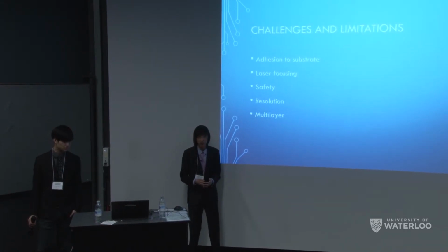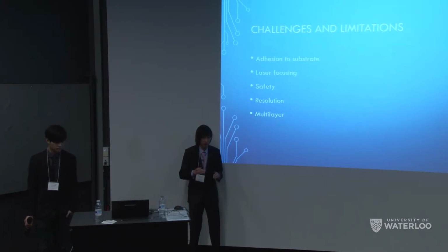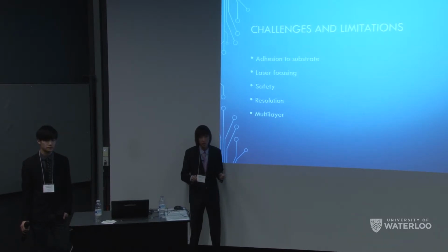Another thing was the laser focusing. As the height of the substrates, or the height of the powder bed, wasn't perfectly uniform in our prototype and in our demonstration, it was difficult to correctly focus the laser so that everything would reach the correct temperatures for sintering. And safety is also a big concern for us. We would all have to be wearing safety glasses while using our prototype and manually manning it, and that was a big design limitation on our part.